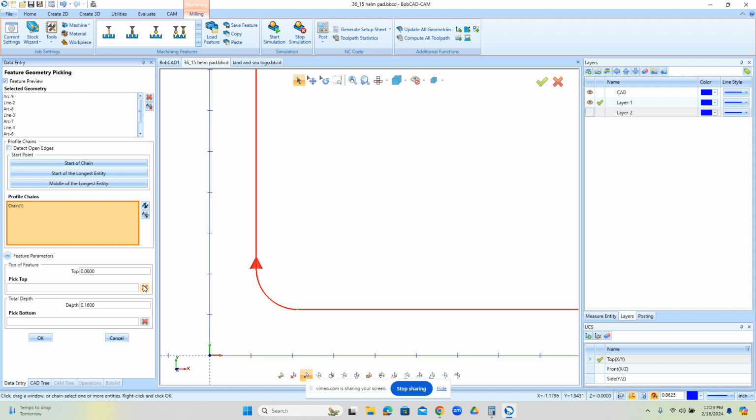Now for this template, it's just a profile with a 1/4-inch cutter, and then it's going to a certain depth. So for us, we need to cut out this profile. So we know that we need to go at least 250, for a 1/4 inch, but we might go a little bit deeper to make sure that we break through the material, so we can adjust this depth cutting value here, and then we're going to choose OK.